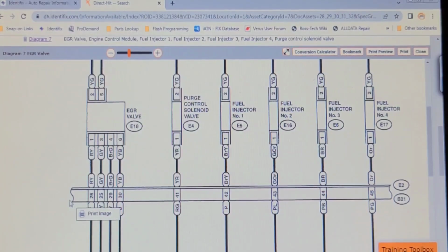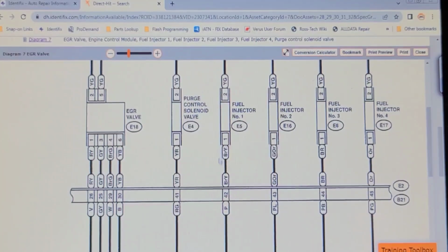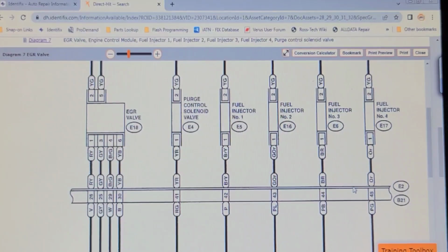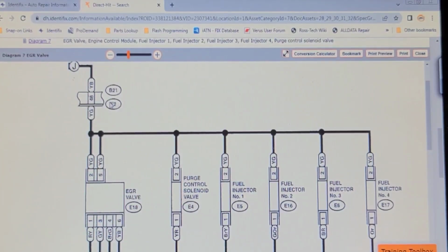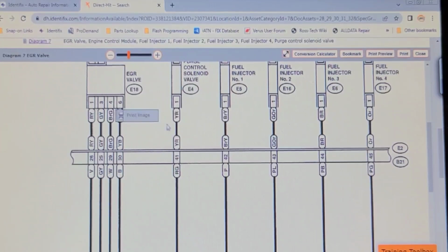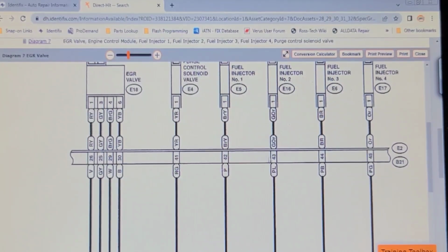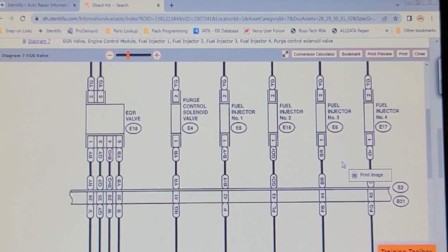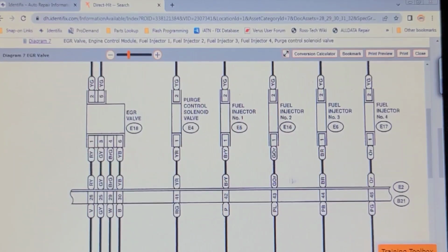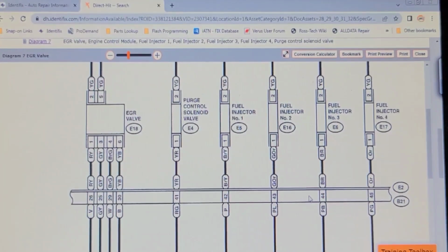So I'm looking at the wiring diagram, and here are the 4 injectors. Obviously testing with a Noid light right at the injector would be desirable, but there's another connector, E2B21. I think that's the one. It's a bulkhead or latch connector on the right rear corner of the engine for when you disassemble the engine. Power through there is pin 48, and the injector control wires are pins 42, 43, 44, 45. That's convenient. I'm going to print this diagram and see if we can access that connector and back-pin one of these pins.